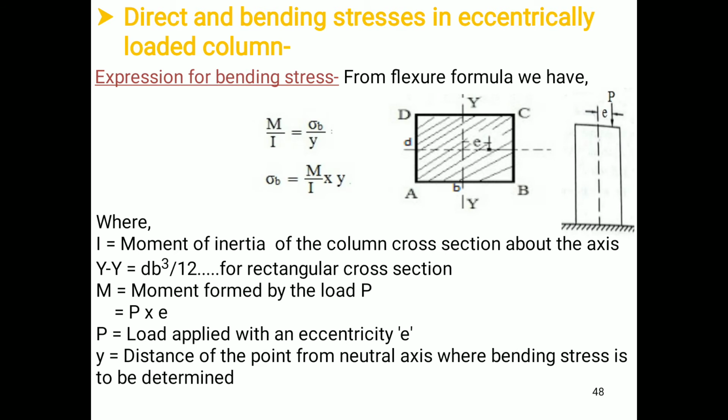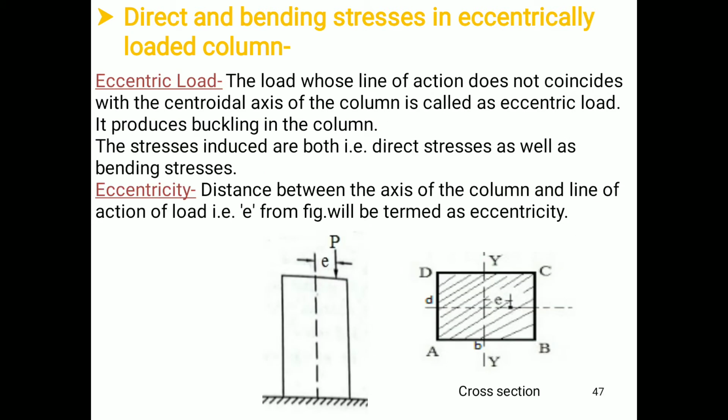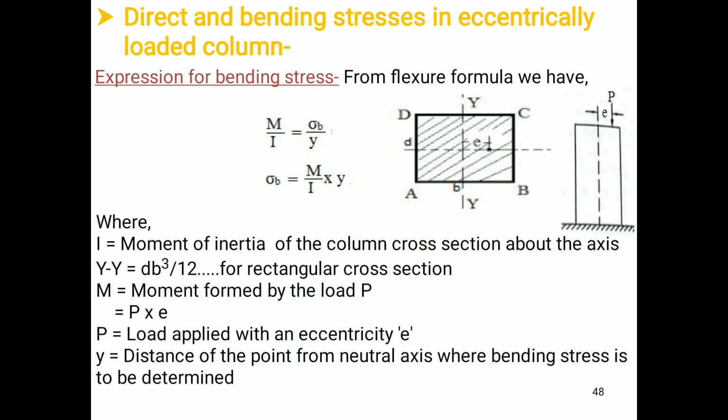The expression for the bending stress can be given by, now as we know that due to the eccentric load, the stresses induced are the direct stresses, which is given by P by A, and the bending stresses, which we have to calculate from the flexural formula. Therefore we will consider the expression of bending stress.